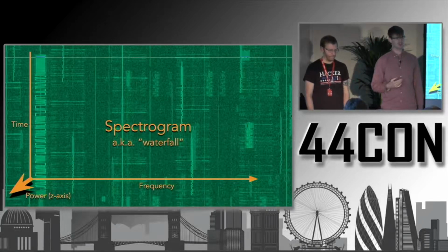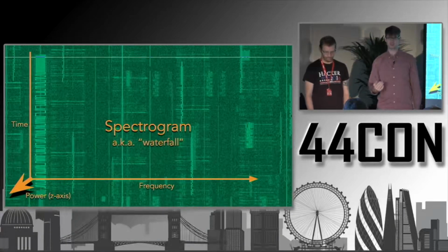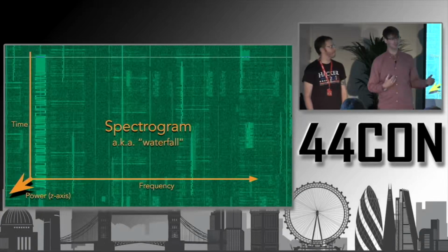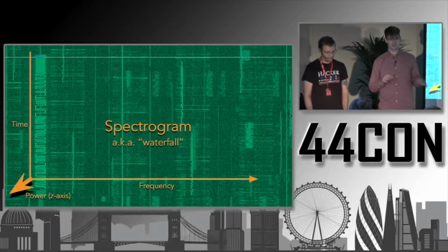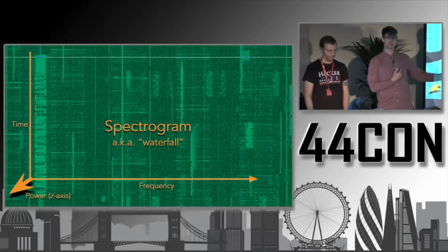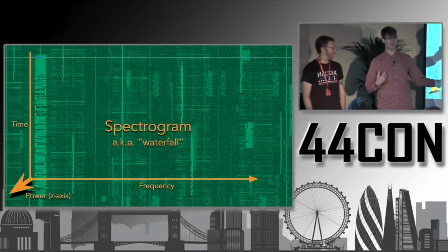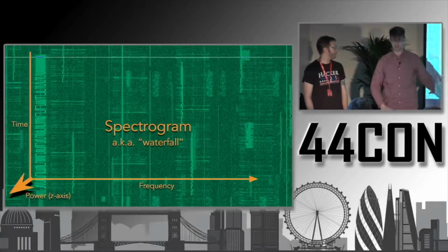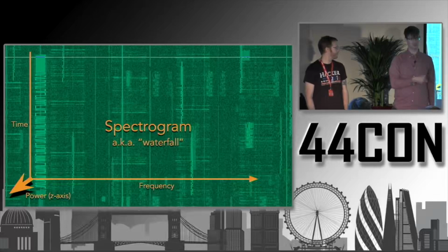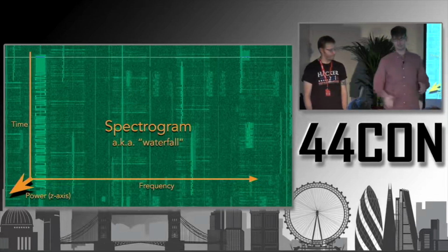A basic property of complex signals is that you can model any discretely sampled signal as a summation of component frequencies. That gets kind of mathy, but essentially what taking an FFT does is allow us to break the signal down into the corresponding parts, and view what's happening at different frequencies within the capture. So we'll be able to use this to visualize what our waveform looks like and zero in on some of the key features here.